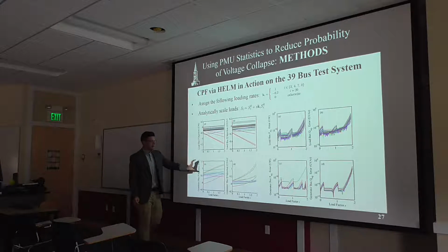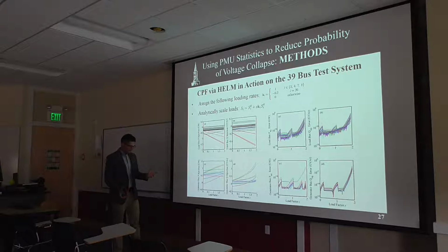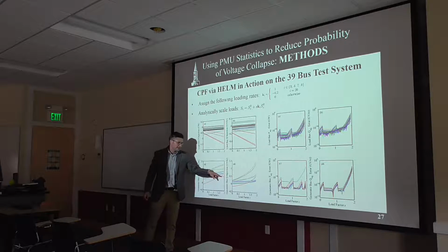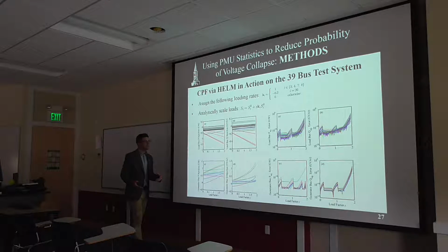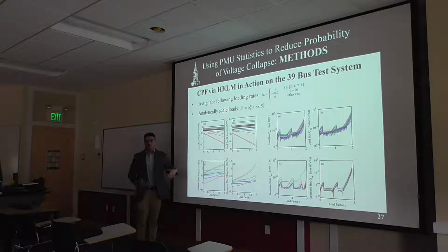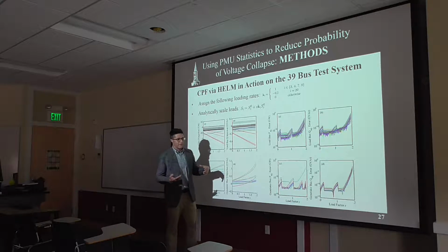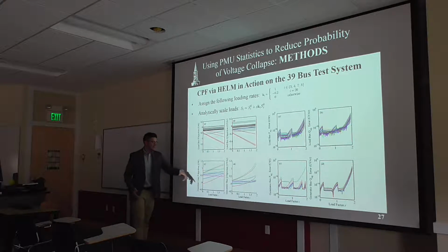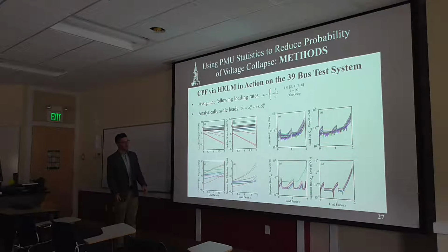And I'm also plotting the active and reactive power injections at the generator buses. What's interesting is that at bus 34, we actually see that the power injection is decreasing as the holomorphic parameter increases. And that is because generator bus 34 is tied to bus 20, whose load is decreasing. So its power injection is actually decreasing, which is interesting.